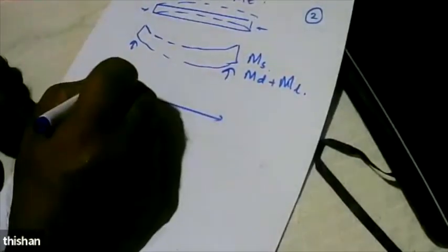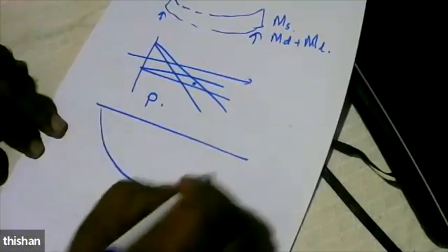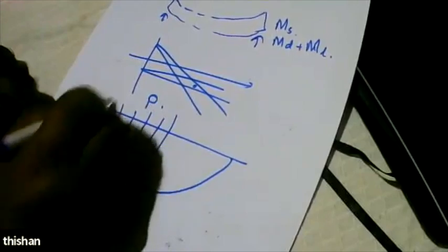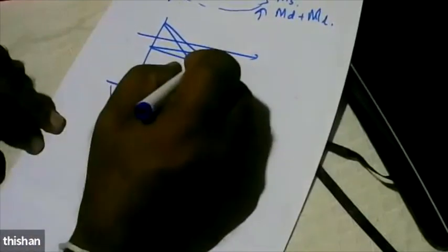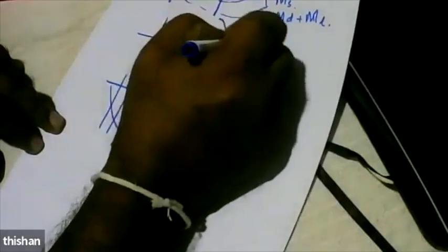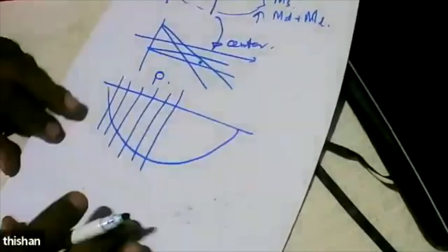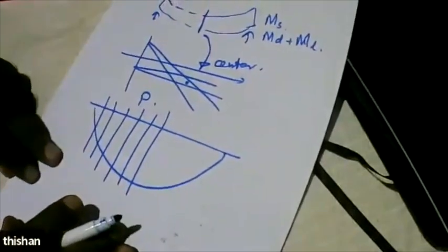And then we said, draw a moment diagram, select a force. And then you have the bending moment diagram. For each section, draw a separate moment diagram and decide how we are going to arrange the cable. So here we draw the moment diagram at the center, because that is the point with highest moment.